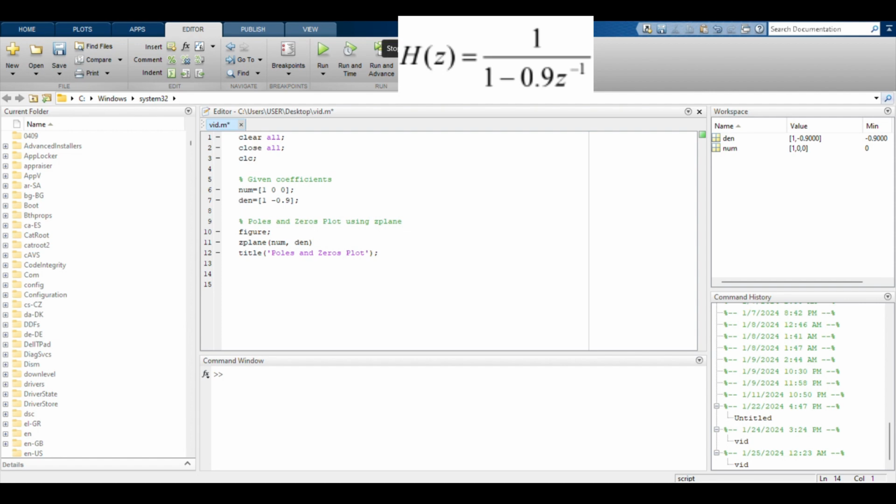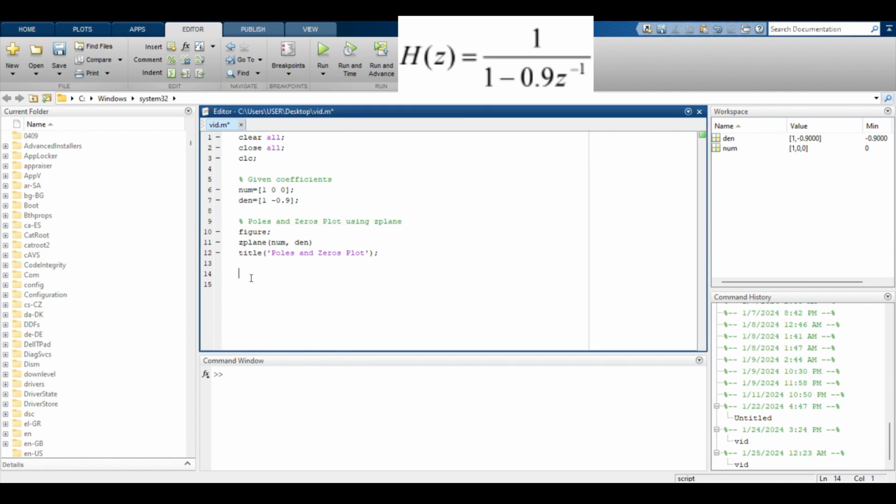For the transfer function given to us, if we consider it to be a causal system, we can study the time domain behavior of the signal. In this video, we will just look at the effect of only a single pole, which means we have just a single pole on the screen. There will be multiple poles as well, but in this video, we will just look at the effect of single poles. And for that, we will use another built-in function called impz.